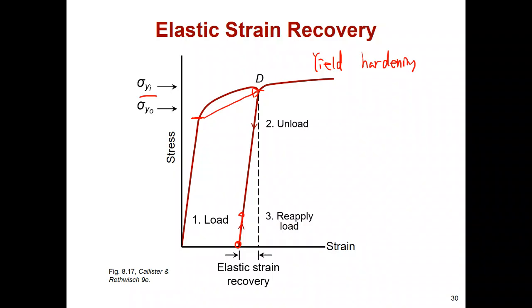It is because they want to increase the yield strength through those loading and recovering cycles. So we call it yield hardening. After the unloading, they recover, but the material is damaged a lot. However, when you apply load again, the yield can be increased more compared to the previous cases.